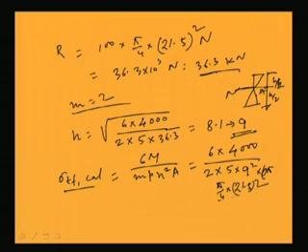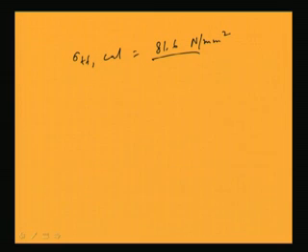After calculating these values, we will finally get 8.16 kilonewton per centimeter square. So, sigma Tf calculated we are going to obtain as 8.16 kilonewton per centimeter square, right. Now, if I change the unit, sigma Tf calculated will be 81.6 Newton per millimeter square.